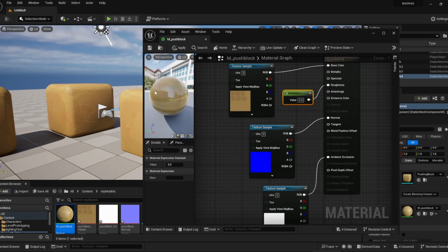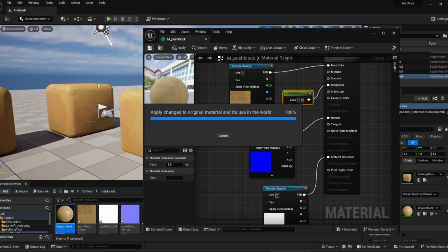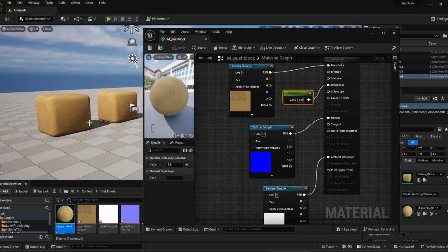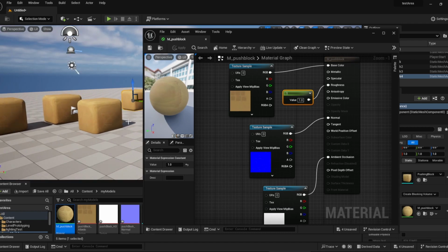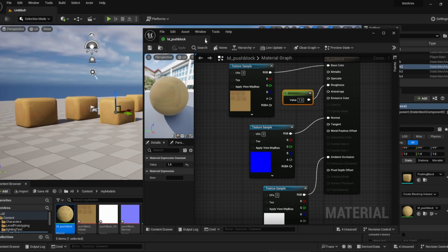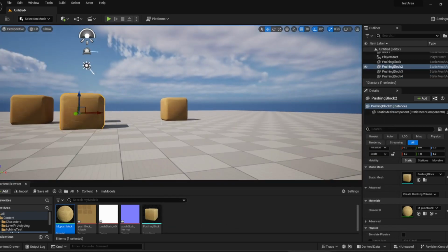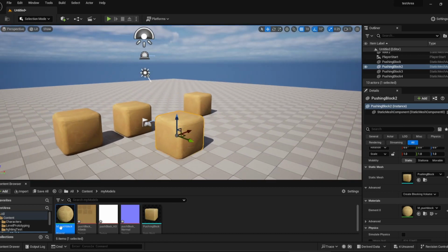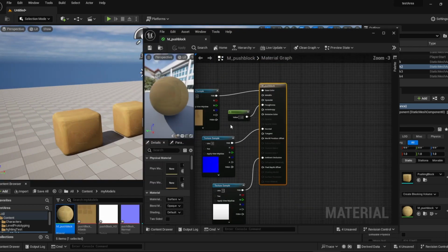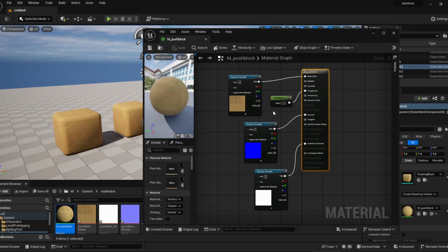This is super shiny now because it has 0, but if I put 1 on there, then it will make it flat, no specularity. So if we just save that off, you should see that shine go. So that's more what we're expecting there. There are instances where you may need to check other nodes that you don't necessarily have a map for, or maybe you didn't export a map for, but that's just how you would set that up there.